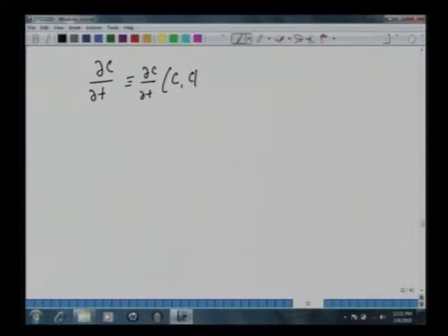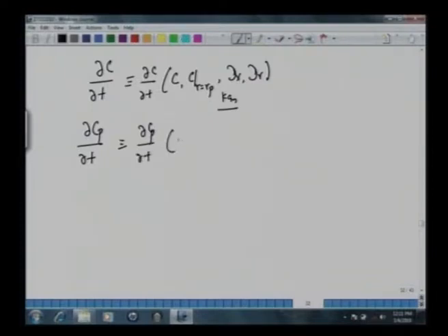We are also talking of concentration at the pore mouth. We have dispersion in X direction, dispersion in R directions. Mass transfer coefficient becomes another parameter here. Okay, then one has to write the balance within the pore of the solid. So this is del Cp over del T. This will also be a function of, say, the gas phase or liquid phase. Then inside the pores we will have Knudsen diffusivity or pore diffusivity. Then at the wall there is a rate at which species is getting adsorbed or dissolved. So CS here is solid phase concentrations, adsorbed phase.